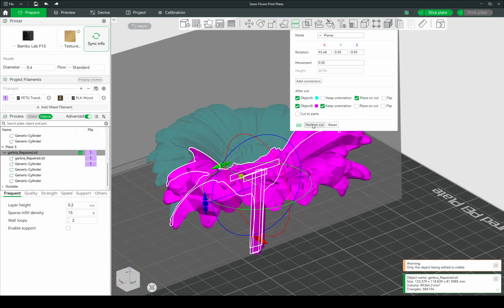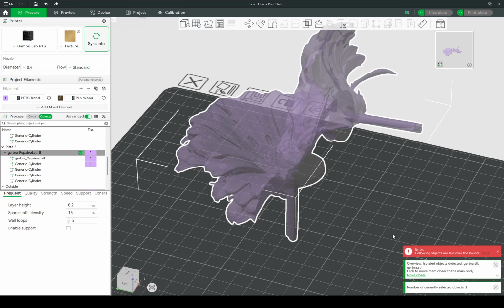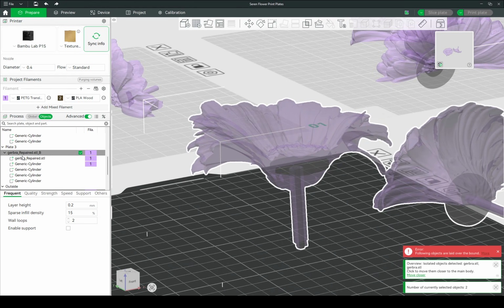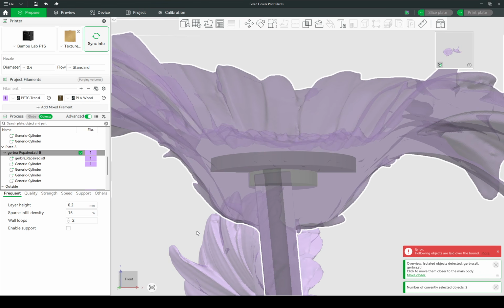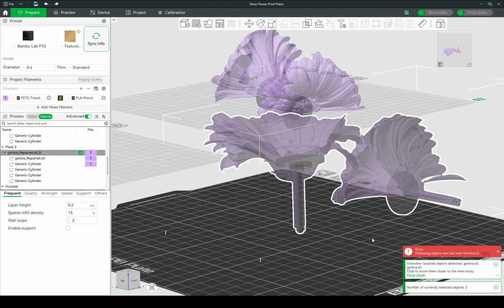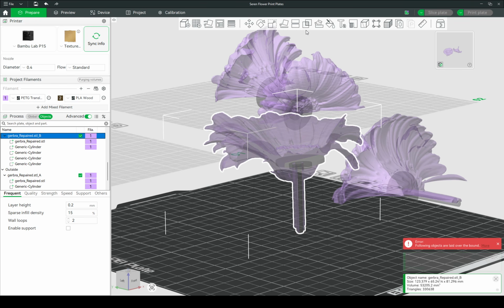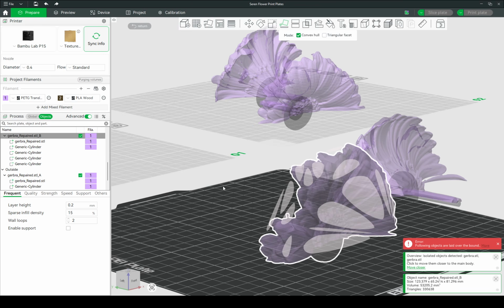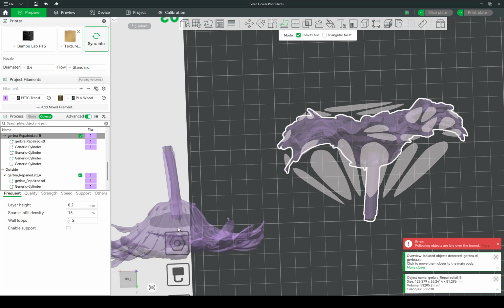And after we get to this point, we're going to go perform cut. What I really like about this process is it preserves the assemblies that we've made in both of them. So now what we have to do is arrange them. So they're two separate STL files, two separate assemblies, and we just go lay flat on this face, and we'll move this one on.